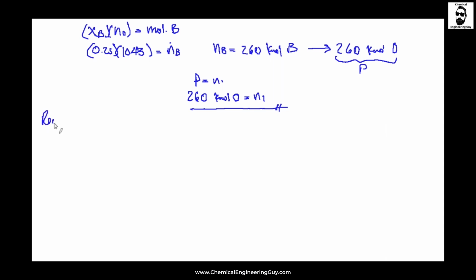So for the recycle of isobutane, we need to do a mass balance. Let's use note 7, which states that there are 5 moles of I for every mole of B at the A flow. So let me calculate the moles of I, or isobutane, in the fresh feed.